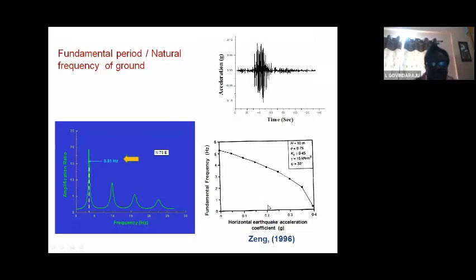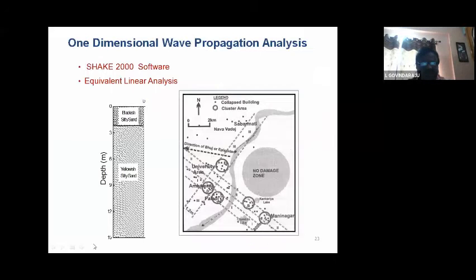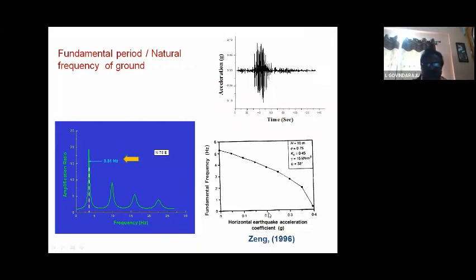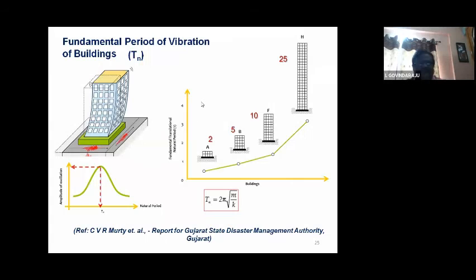Here, we again cross-checked with Zhang, to see whether our analysis is correct or not. Please note that here it is approximately 0.11 g. The depth of the soil is 10 meters, but we took around 15-meter depth. If you make an approximation at 0.11, we are getting nearly 4, or 4.2. But if you go slightly beyond, we get close to 3.51. So nearly 4 and 3.51 are almost matching with each other, as proposed by Zhang.